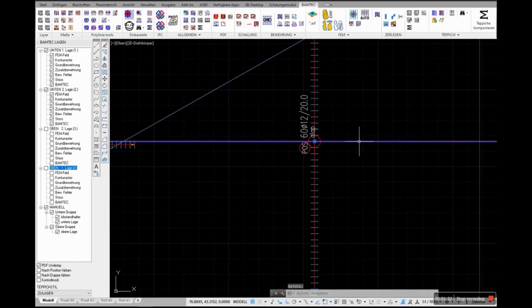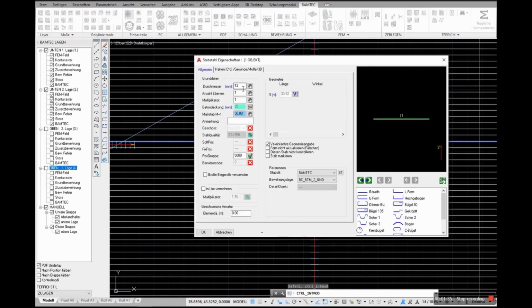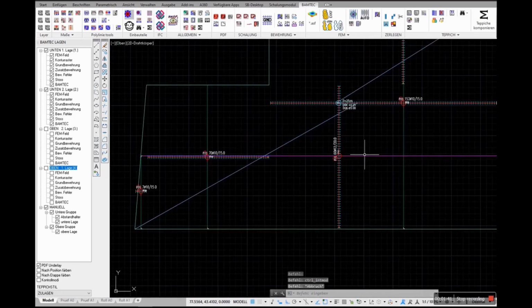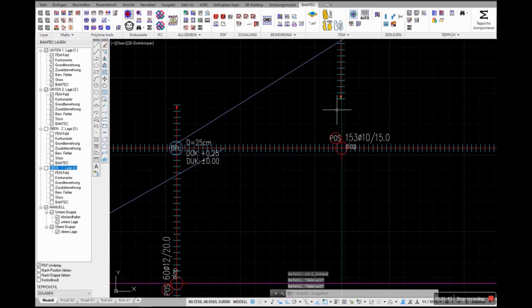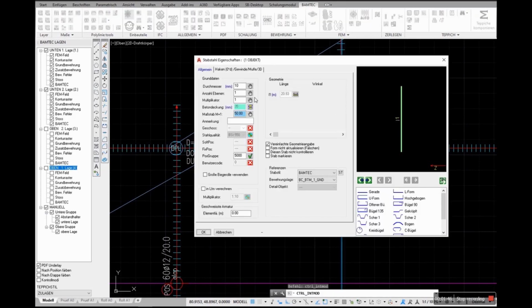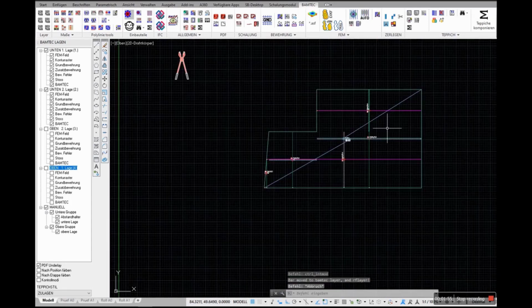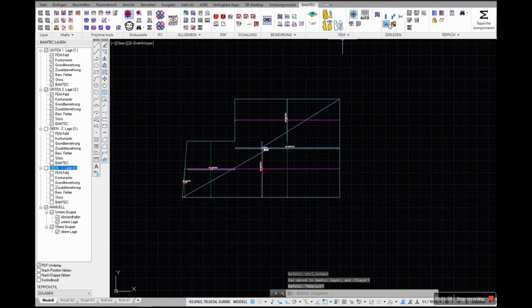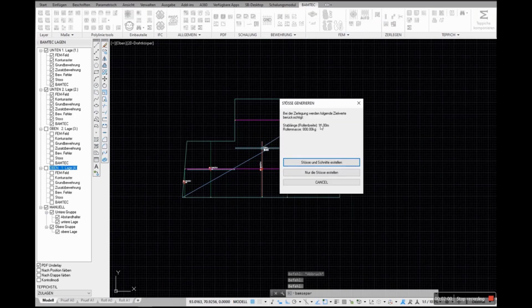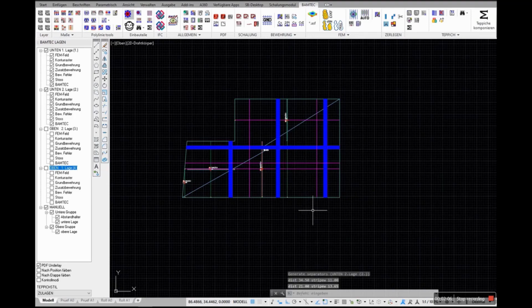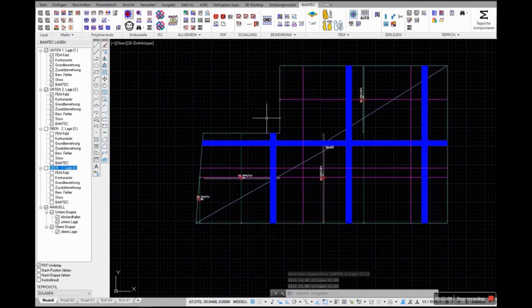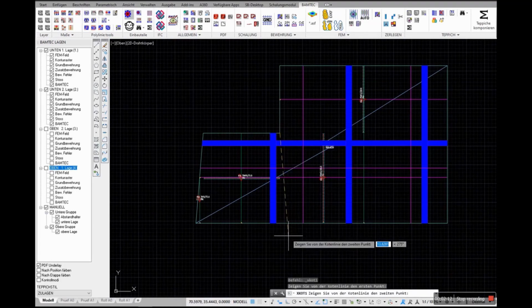That means now we've got straight bars in our reinforcement layer, in the cross section and in the distance determined. Variable lengths have automatically been chosen as well. Once again, we check how the reinforcement is laid on the screen, and we can configure everything again. Every layer in reinforcement can be shown as an individual layer. That is also good for the blueprints afterwards, for manufacturing the blueprints, and then we can get suggestions for the manufacturing of carpets.